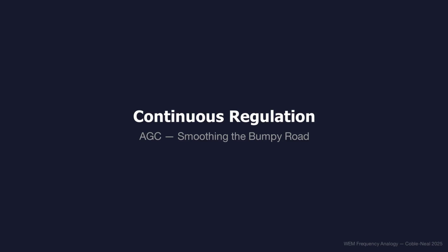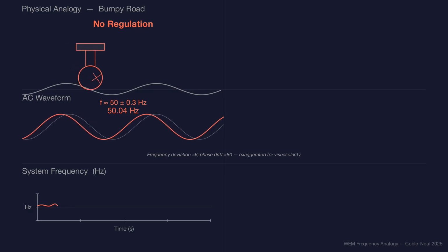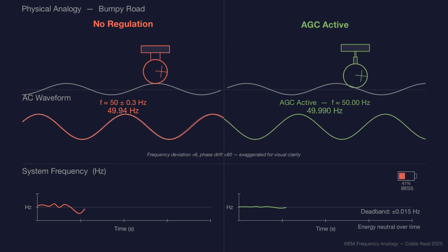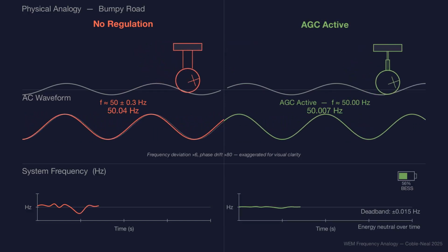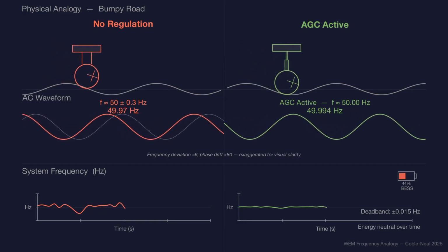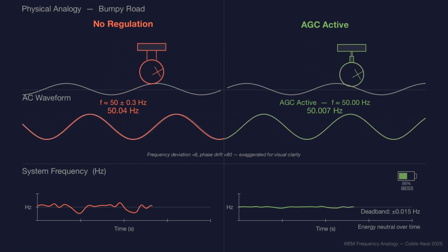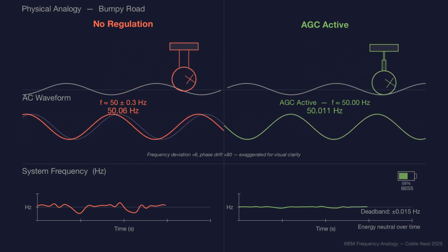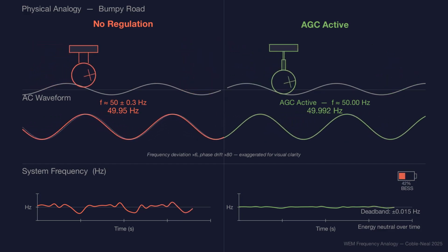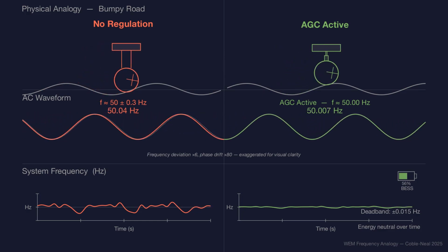Of course, electricity systems experience many disturbances. In fact, there are so many disturbances that a continuous regulatory service is required. This regulation service requires controllable machines to be adjusted almost continuously. Note that in this side-by-side comparison, system frequency varies much more in the governor-only system on the left panel than in the actively managed system on the right. In the WEM, this continuous balancing service is known as Regulation FCAS, one of 5 frequency co-optimized essential system services that the market and system operator procures to keep the system stable.